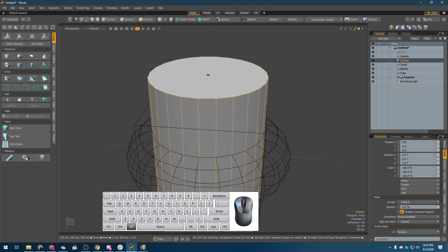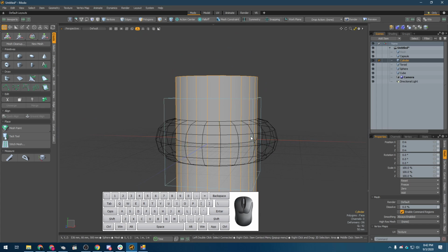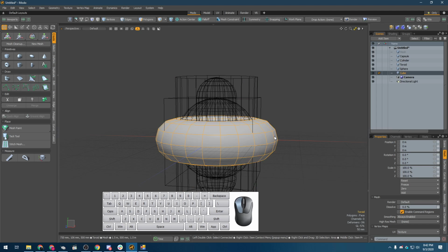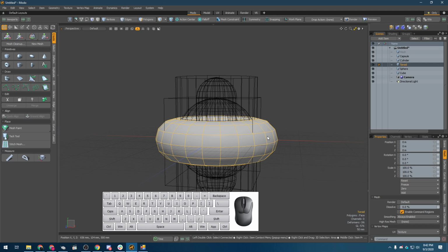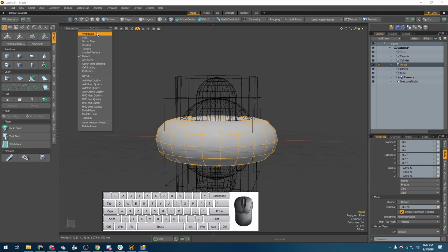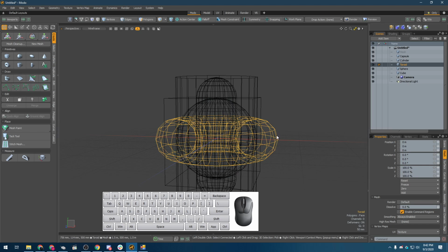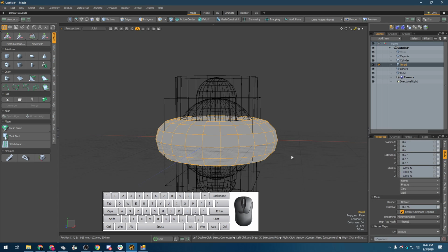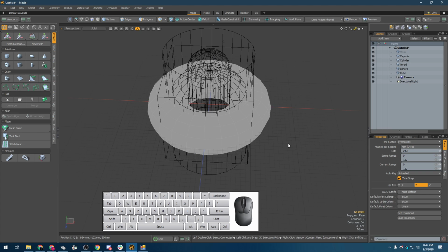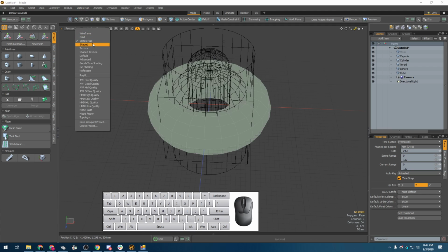Now, just a note about the display here. The grid-like items that aren't selected are being shown in what's called a wireframe view. So it is the frame of the object made out of a wire. And there's a bunch of different options for how we look at our scene, and most of those are found under here where it says default. If I click that, if I click on wireframe, all the objects, including the selected objects, are going to be in this wireframe view. I can look at it as a solid, in which case there's no sense of lighting, it's all just a flat color. And there's a bunch of different modes here that you can play around with.